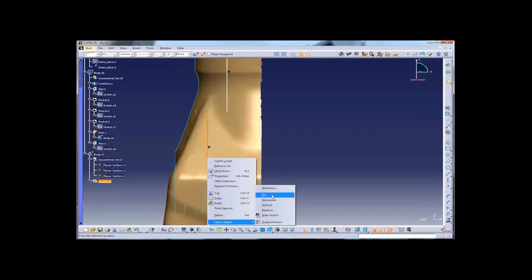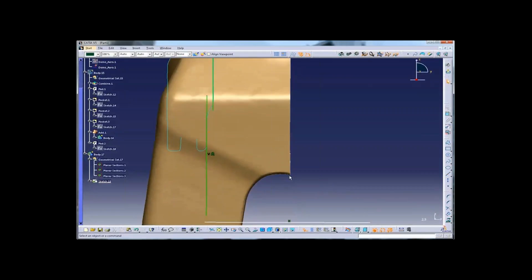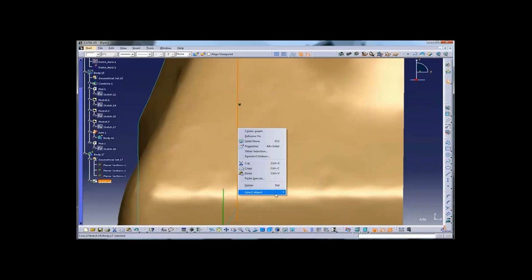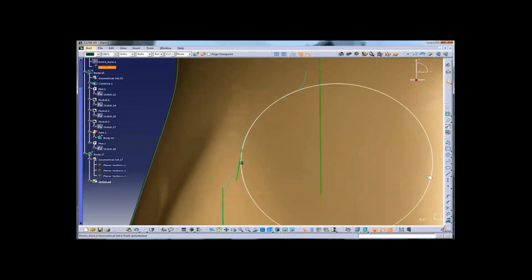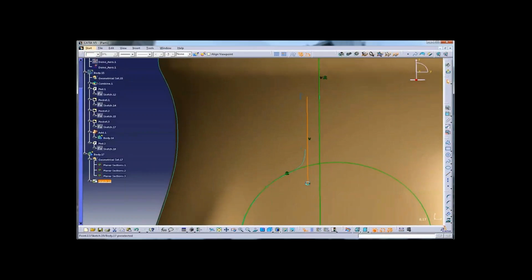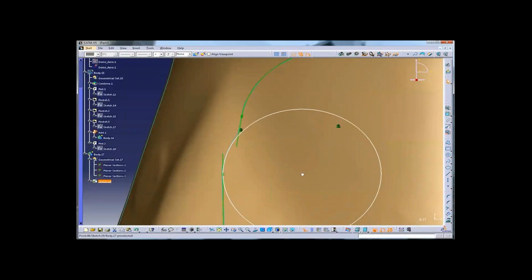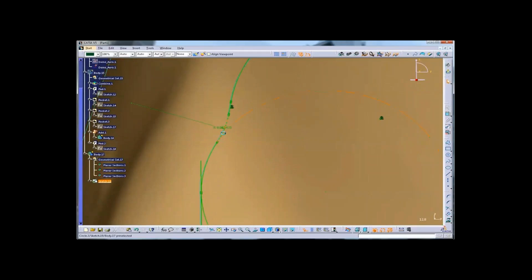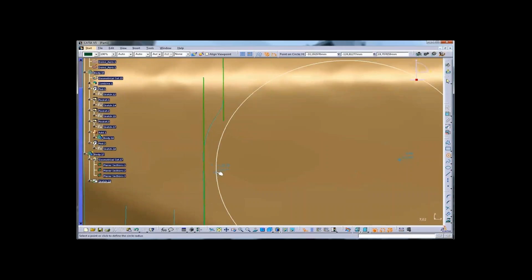Now for the inside of the part, we need to remove some material. So I'm going to create once more another sketch to be used for a shaft, but this time to remove material. I'm going to still use my cross-section that has been previously done, but this time the inner profile to create my sketch. Again, you can see the cross-section in light blue in opposition to my sketch, which is now getting all green. Almost done now. A few details, corners and edges.